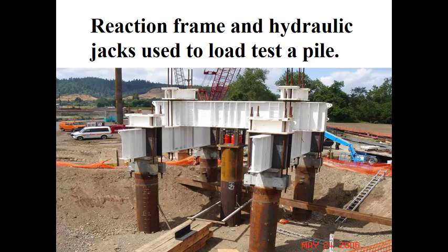What you will need to do is to drive some piles and then have these jacks positioned for loading the test pile to see if it's actually supporting the load that you calculated from the engineering design stage, or it's giving up and you need to further drive it down in order to support the weight. Because as I said, in some situations the bedrock that we try to reach will be far deeper and we will rely on the skin surface friction.